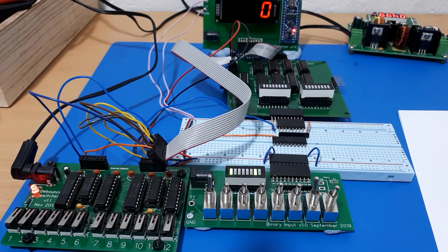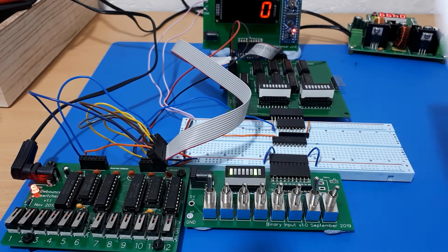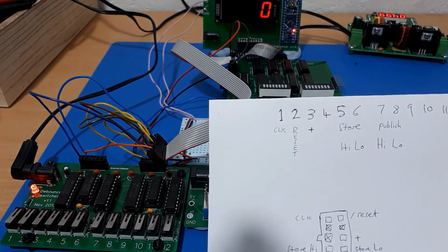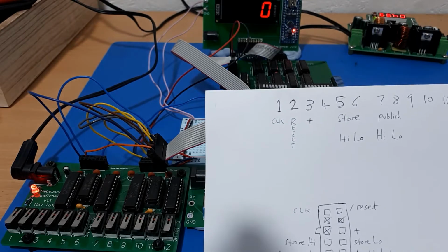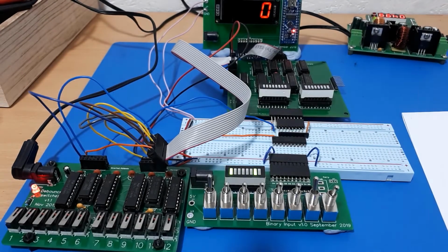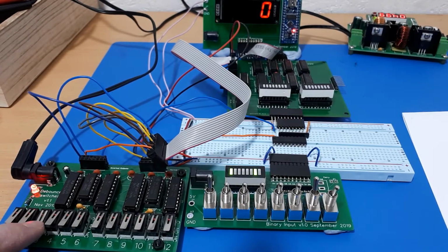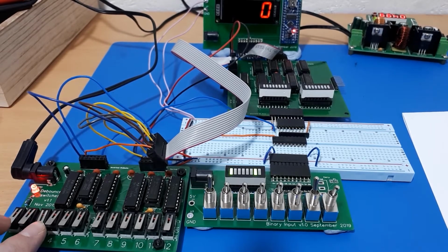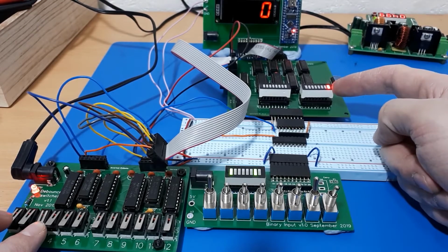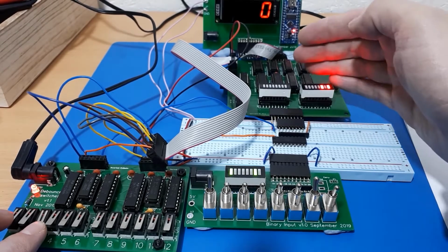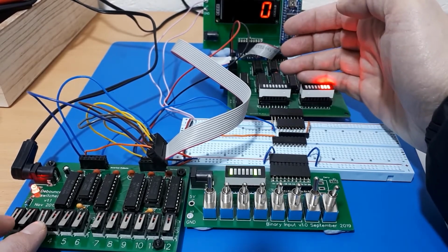Right, simplest of the lot, we want to be able to increase the program counter. So that's button 3, and also we need to do the clock, because how this thing works is it's synchronous to the clock. So if we hold down 3 and do a clock cycle, we see that the program counter is increased to 1. Do another one, and it increases to 2. Then it increases to 3, and it's going to keep counting up like that. Is that clear? Yeah, I think that's pretty clear.